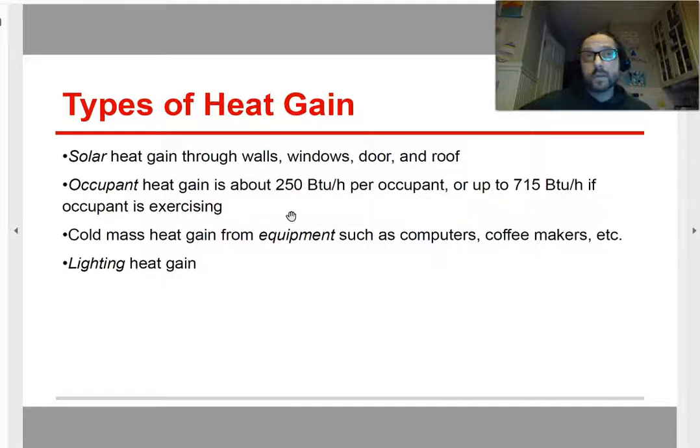Industrial buildings as well. Think of a big factory that has all kinds of huge mechanical equipment operating all the time. That's a significant internal load. That's heat that will end up heating the building. So in the summer, you can imagine that's a problem, right? You have to make up for that extra heat. In the winter, it's actually a good thing, because you can keep the building warmer without providing as much heat. So just so you know, internal heat loads are really important.